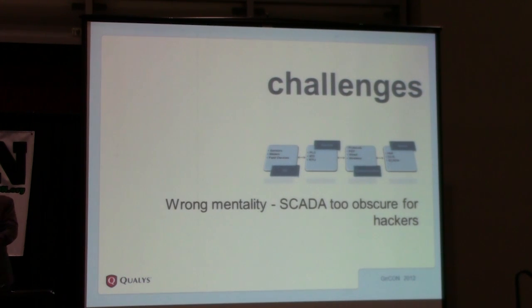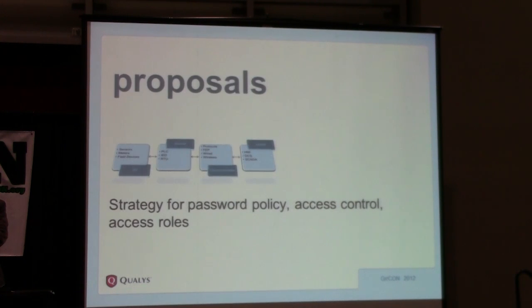It used to be a wrong mentality that SCADA is too obscure to be hacked, but I think Stuxnet and Duqu and all these viruses have helped a lot in changing that mentality. So some of the proposals that I have here: do simple things like strategies for password policies, access control for access roles, and some strategy for software upgrades and patches, if possible.